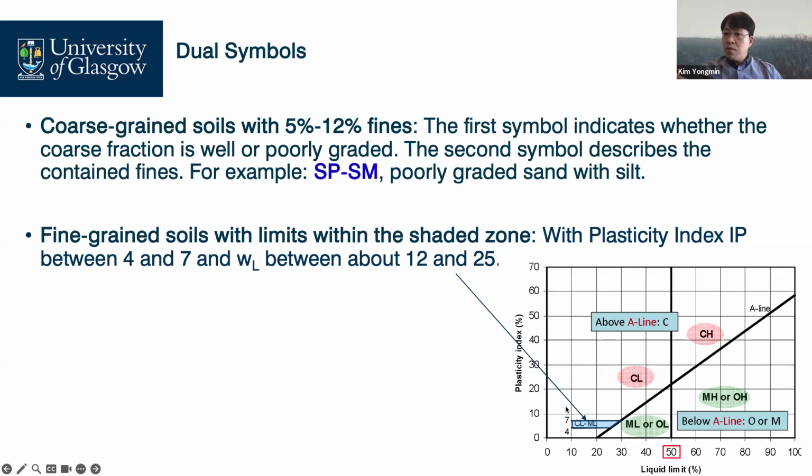But the liquid limit and plastic limit tests are quite empirical, right? In the tests, how do you control these micro numbers, 4 to 7? There should be human error. That's why even if we have clear charts in terms of specific numbers, anytime our soils fall on a dual symbol here, here, here, here, you need to understand these uncertainties.